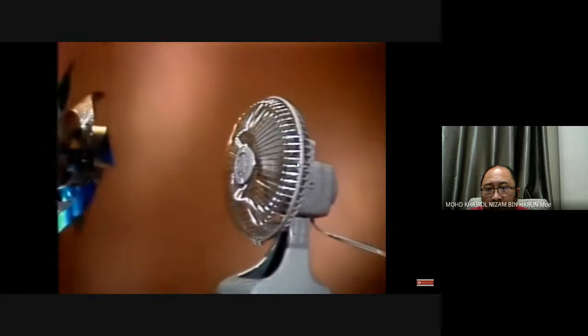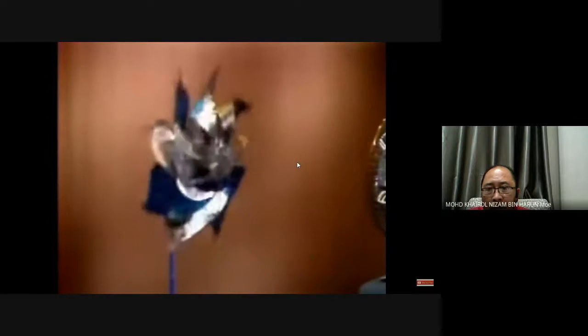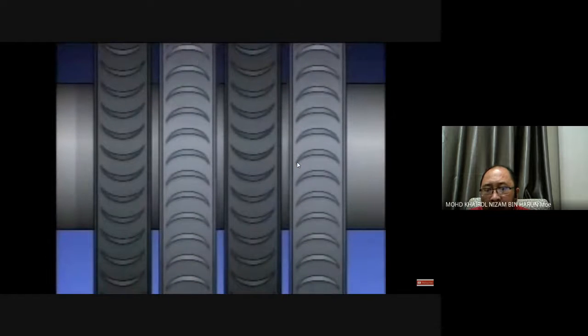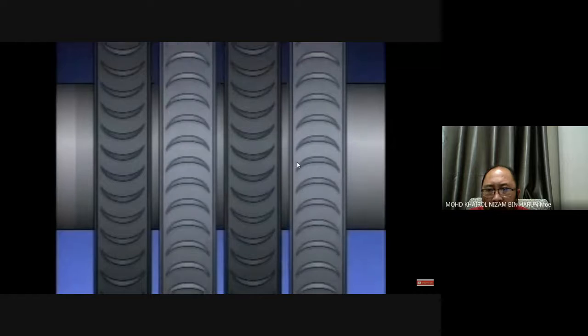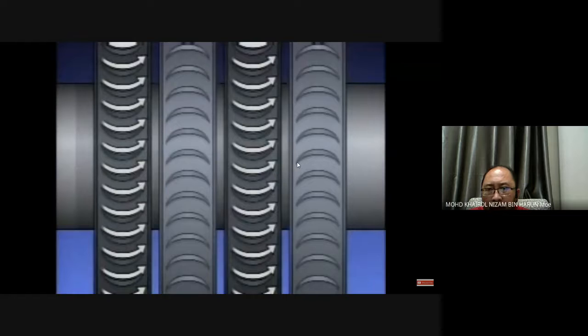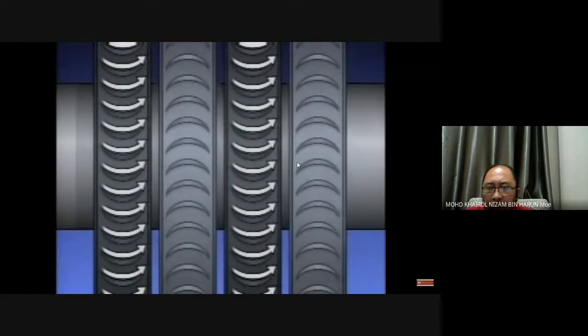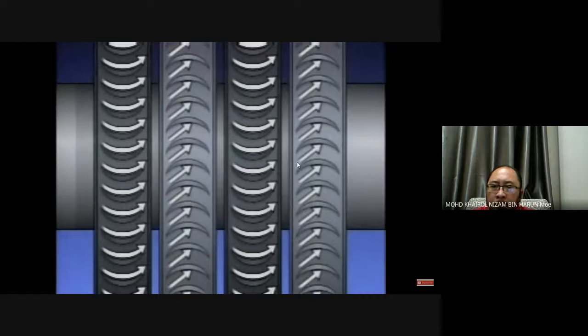Impulse blades work in a manner similar to the blades of a pinwheel. Air traveling in one direction strikes the pinwheel blades and pushes them out of the way, causing the wheel to turn. With turbine impulse blades, a similar thing happens. This simplified illustration shows the configuration of turbine impulse blading, with the rotating blades and the stationary blades or nozzles. As high pressure steam is forced through the stationary blades of a diaphragm, it speeds up. The steam striking the rotating blades causes the wheel to turn. Since the wheel is attached to the shaft, the shaft also rotates.